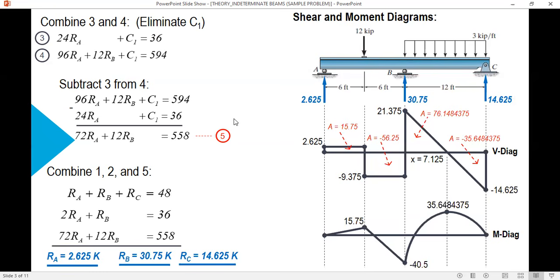Okay, so double integration method, this is where you get the additional equations. So if there are two redundant unknowns, or simply the problem is indeterminate to the second degree, then we will have two additional equations. So there are four unknowns. Same lang, no? Either you can use method of elimination or Gauss Jordan or determinants, depending on the problem. But mostly, you can solve the reactions by just using method of eliminations.